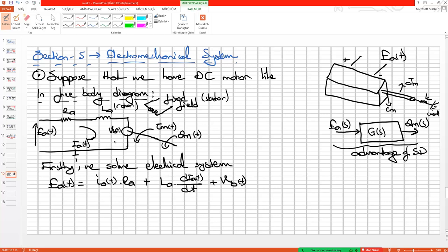This is the motor voltage in here, okay? And as we know the electromechanical system or the energy conversion, we can write this: v_b is equal to what? The K_b times d theta_m/dt. Angular velocity is proportional with the voltage v_b value, okay? And so this K_b comes from the electromagnetic equations or the simplification of these terms. And also we can write the torque T_m is directly related to the K_t times i_a(t). We can easily linearize the whole system based on this information.